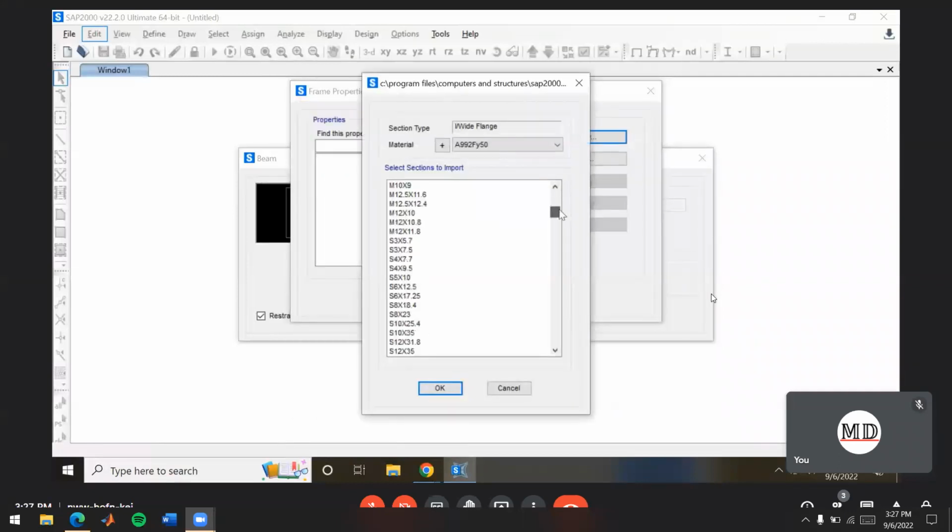Now, there's a lot of different wide flange or kind of eye-shaped members here. We've got all the piles, and those are the HP shapes. We've got some miscellaneous M shapes. We've got the old American Standard I-beam shapes, and those have been remarked as S. And those are from way back in the day. And then we have all the wide flange W shapes down here.